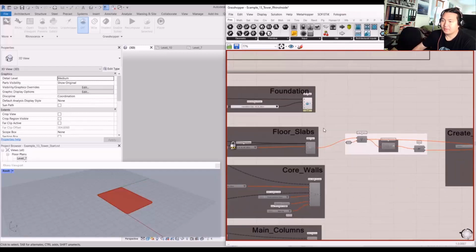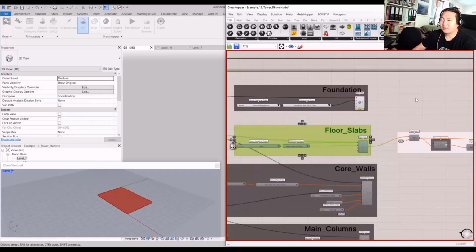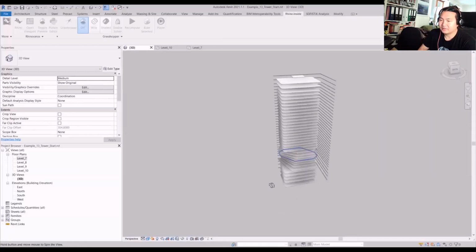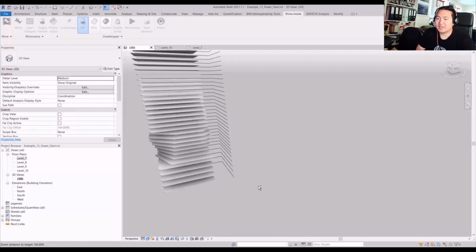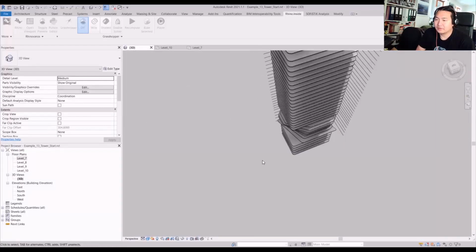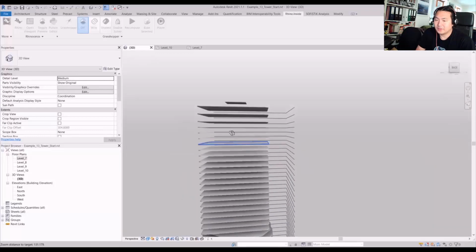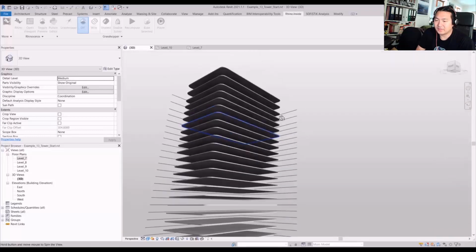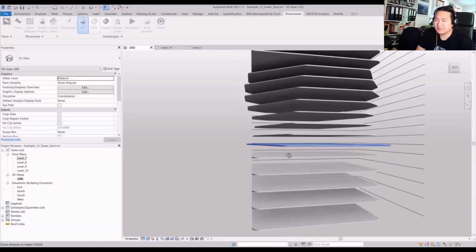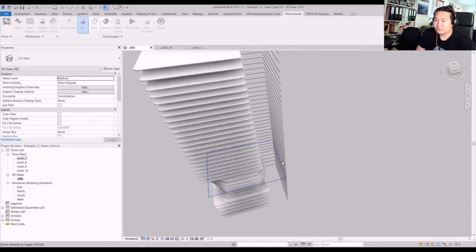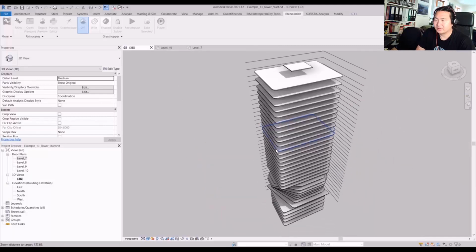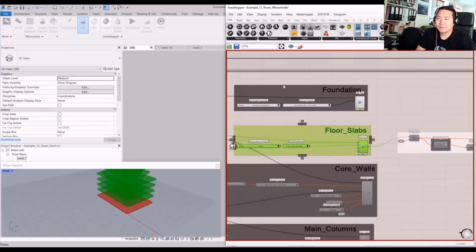and each slab will contain an opening family. So the next group of script will define the location of the insert family, the opening family, and also the size parameter. We can control it. So as you can see, all the slabs are just generated within a second. The performance is great, and yeah, the geometry also looks really great in this Revit viewport.